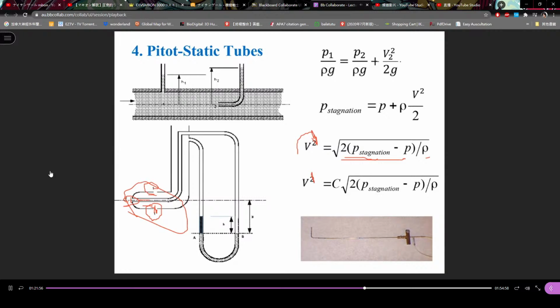So using this, you can see a very small tube, but it's a double shell inside, 2 parts. Then we can measure the pressure difference, stagnation pressure and the static pressure. Here is stagnation pressure. Here is static pressure. Or we use 1 unit. It's 2 different pressure meters. This is 2 different, but we can combine these 2 together for this pitot tube static pressure measurement.